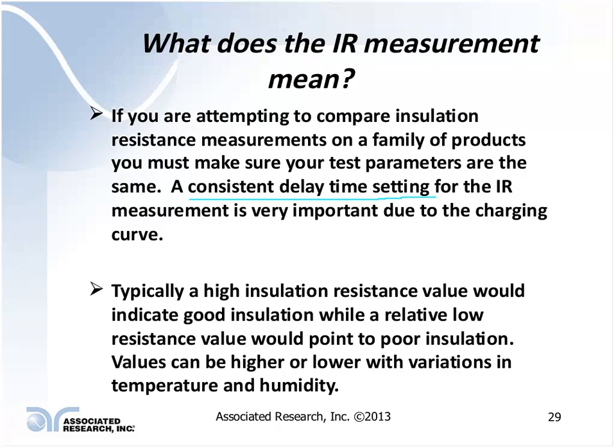So if you're trying to compare insulation resistance readings, I recommend you write down the model number of the equipment that you're using, so you're essentially comparing apples to apples. If you can use the same type of instrument each time, it is very helpful. Otherwise, you may want to make sure you wait long enough until the charging current stabilizes before you take a reading, to make sure that you are looking at a consistent reading.